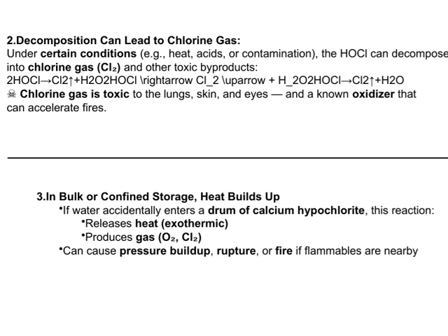Chlorine gas is very toxic, dangerous to the lungs, skin, and eyes. Plus, it's a strong oxidizer, which means it can speed up fires if they occur nearby. So, understanding these reactions and risks is crucial for safe handling of calcium hypochlorite in storage.